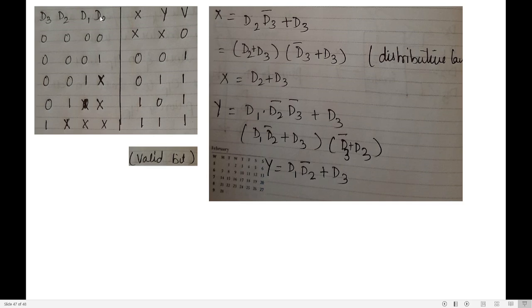In this case, first D0 will be high and the rest will be zeros. So what do we do? Since it is D0, we write 0, 0 as the output. D0 is high, and since any one of the inputs is high, we write that this is a valid condition. See the next condition.